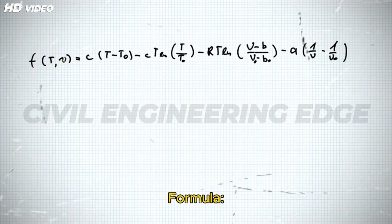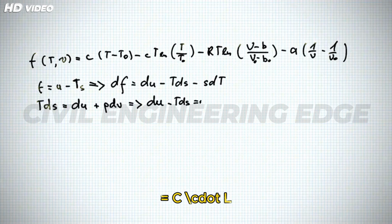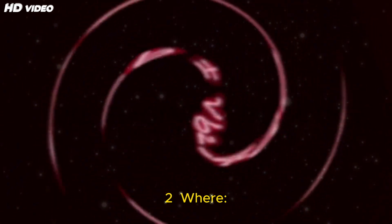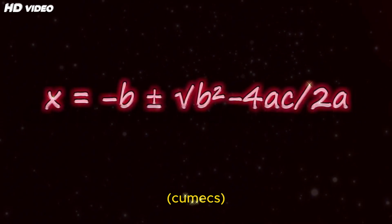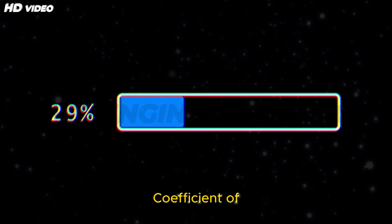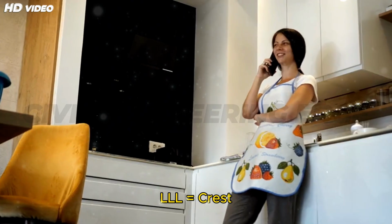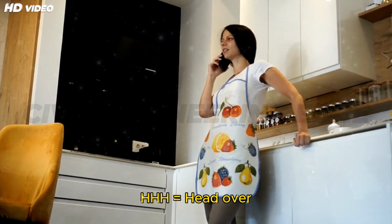Q equals C·L·H^(3/2), where Q equals discharge, C equals coefficient of discharge, 1.70 to 1.84, L equals crest length, H equals head over crest.